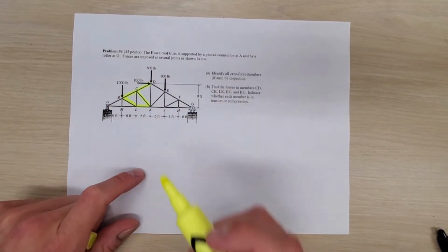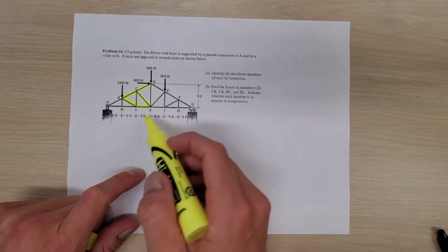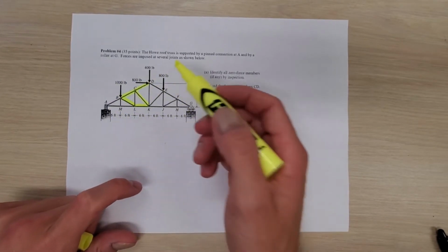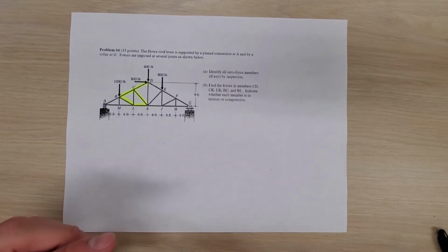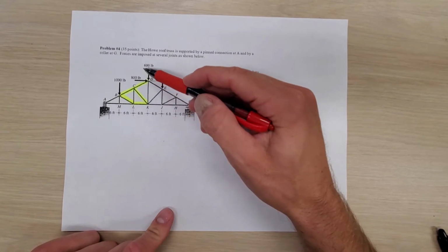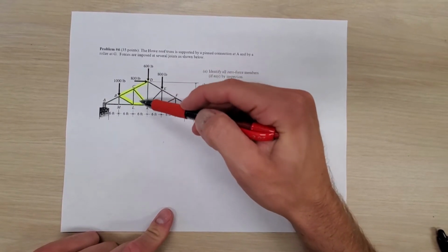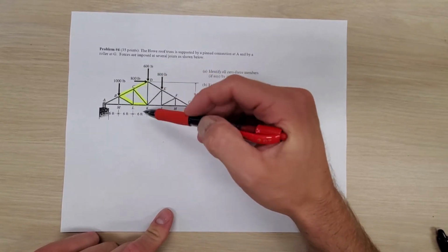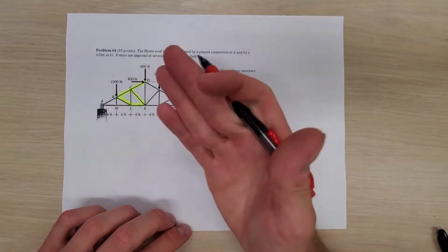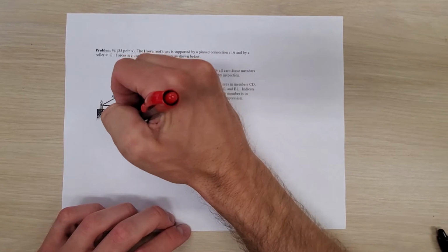BL right there. So now we can see that all of the truss members that we're looking to solve for are over here on this leftmost side. This is going to tell us how to solve the problem. And what we should try and do is take a method of sections cut through these three members right here, because it's always very effective to try and cut through three things when you don't know what they are. So we'll draw a dotted red line,